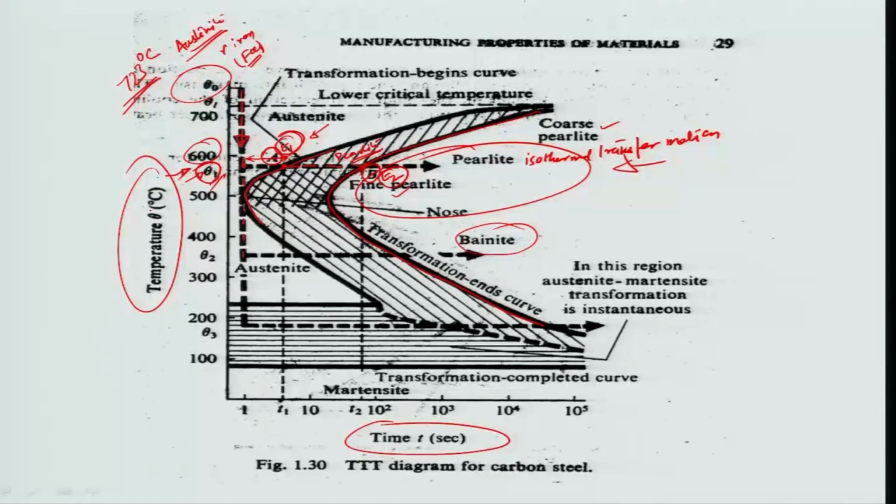The transformations corresponding to the other temperatures theta 2 and theta 3, if the sample is allowed to cool beyond theta 1, are all shown here. For example, if it directly goes into a rapid cooling mode where the time spent in cooling is very low, you can see that it enters into this martensite phase. Okay. So, this is martensite. So, whatever I was showing diagrammatically in terms of structures and cooling is being represented in this TTT curve as one snapshot. Now, you can change your rate of cooling and attain any structure that you would like for the engineering material.